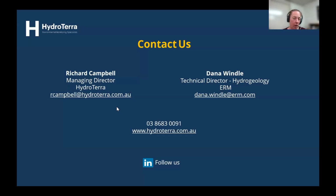I often start at 5-minute intervals, but it does also depend on the tidal cycle. So Southern Australia has different tides to northern, western, eastern, same thing. So it depends if you're getting 2 tides a day, 4 tides a day, massive tidal variations. So again, site specific basis, but yeah, 5 to 15 is probably what I'd start with. And again, it depends what you're seeing in your groundwater and your tidal data as well.